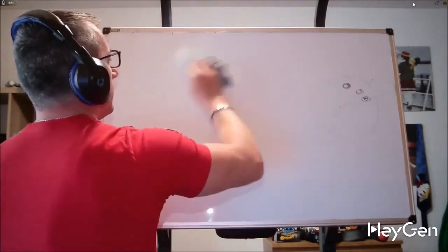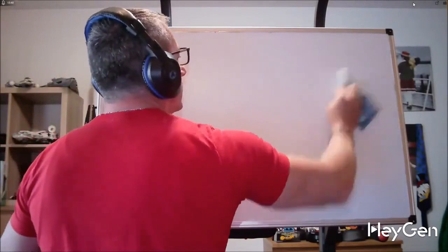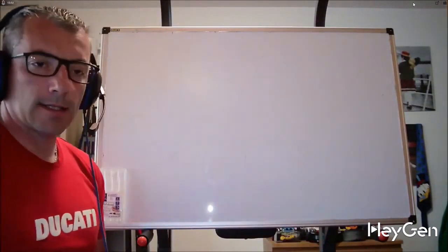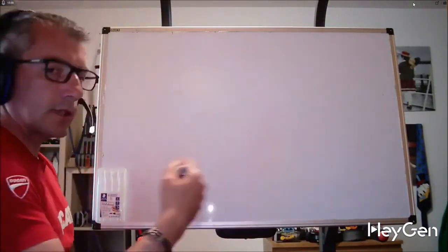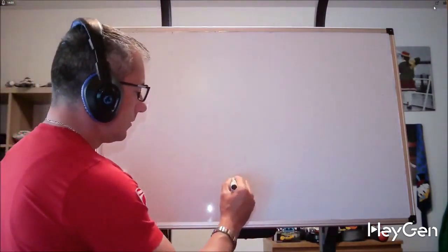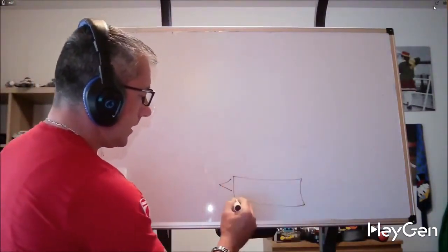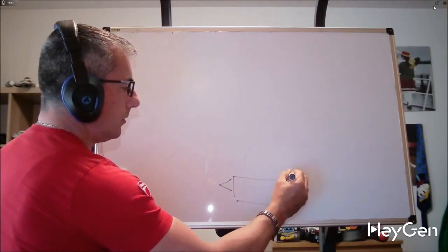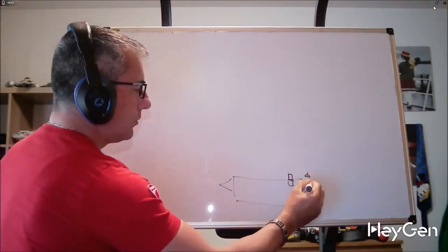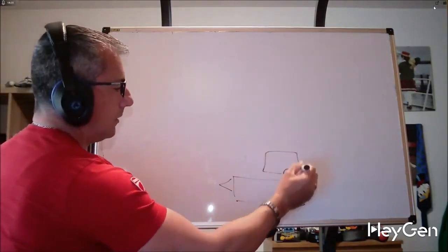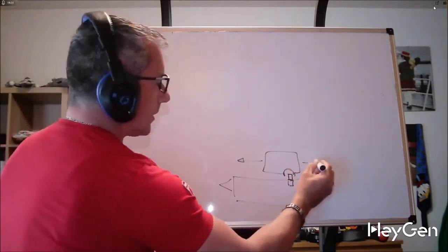I don't know if you've ever worked with machines equipped with a tailstock or a mobile steady rest where the tailstock needs to be attached to the carriage to be moved left or right on the machine. Normally this tailstock is moved. This is my tailstock. From the turret, here we have a peg. The peg goes up and down lightly. When the turret positions itself exactly at this specific spot, it grabs it and gently moves it left and right.